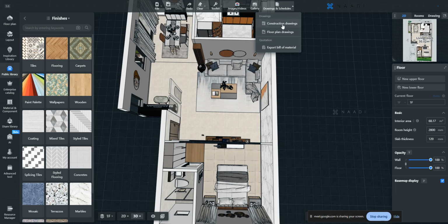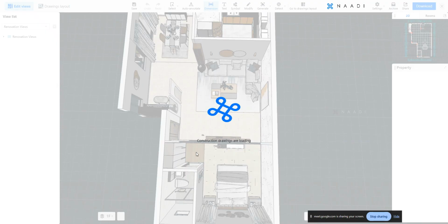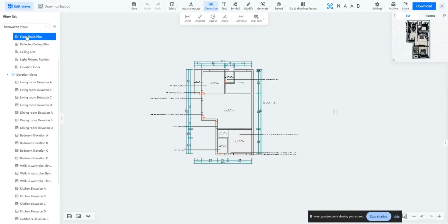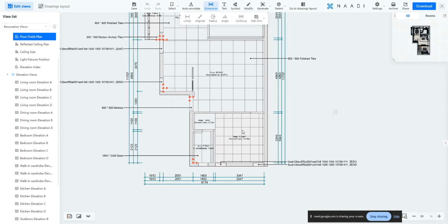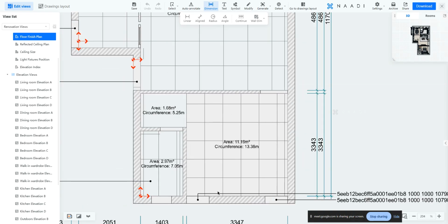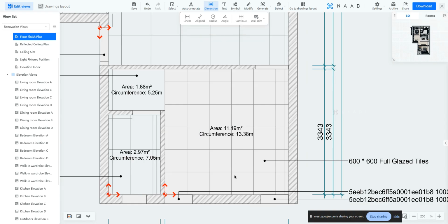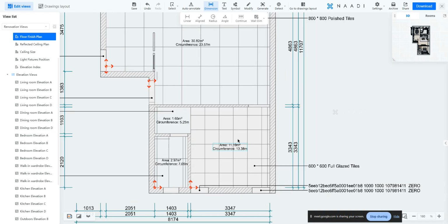Once that is done, now if we just go to your construction drawing, before if you notice in that floor tile layout for the bedroom, I didn't have a floor tile layout being defined there, right? So now since we added it, now can you see the same floor tile layout is defined now and it will be on point here. So this is what I was referring to. Okay, so make sure that your floor tile is precisely taken to the point. Now can you see here? And did you notice what I did now? I made some changes in the model here. Okay, so yes, it will automatically get updated in the drawings here. You don't need to worry about it.